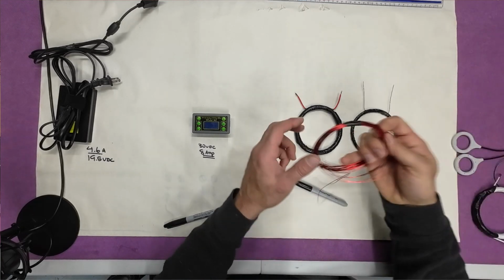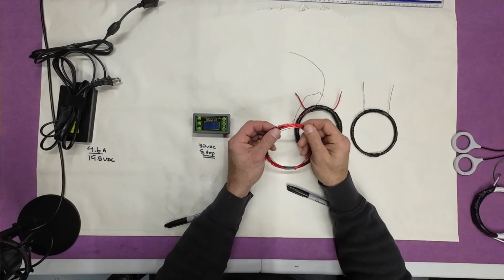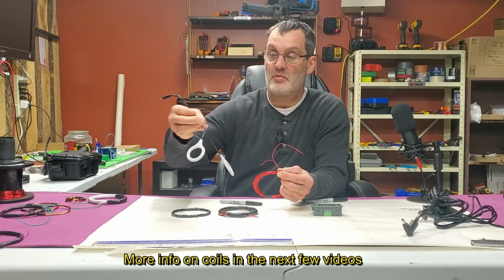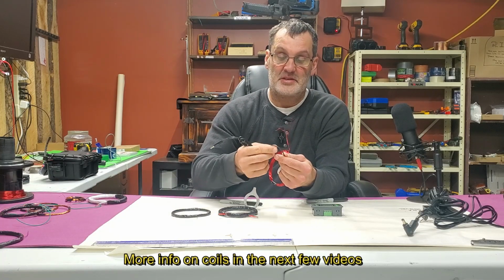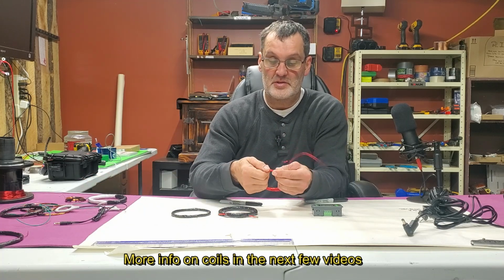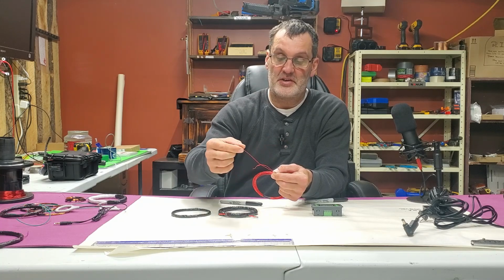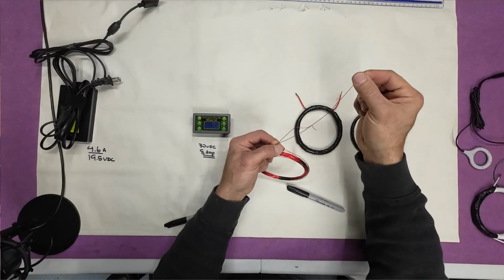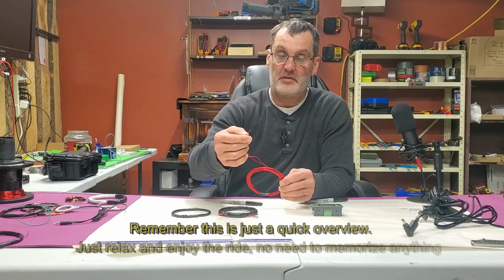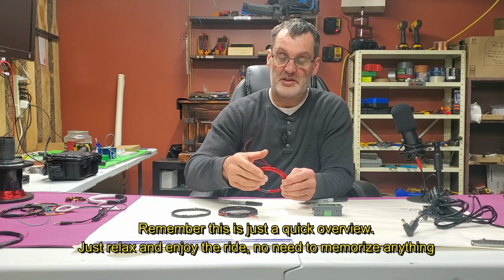So, your coils, you always want to make them out of magnet wire. The reason why you don't want to use wire like this is because there's so much insulation on that. You want your wires to be as close together as possible. Now, I know this looks bare to you guys. It's not. There's a varnish on top of that. There's a thin layer of insulation, and you have to sand it off or burn it off to make your connection, because there's insulation right now.